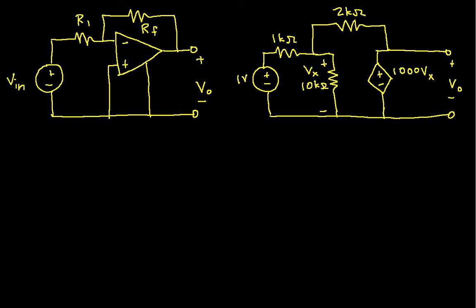On the left here we have a circuit that shows an op-amp. The op-amp is this triangle here. And the idea is that the output voltage, the voltage at this point, is proportional, typically with a very large constant of proportionality, to the difference between the voltage at this input and the voltage at this input. This is called the non-inverting input, and this is called the inverting input. And with these op-amps and the judicious use of resistors, you can come up with useful feedback combinations that make a lot of very useful circuits.